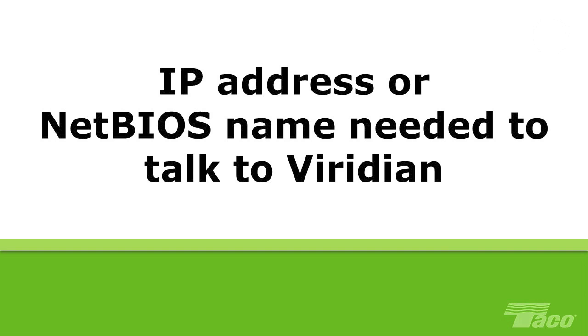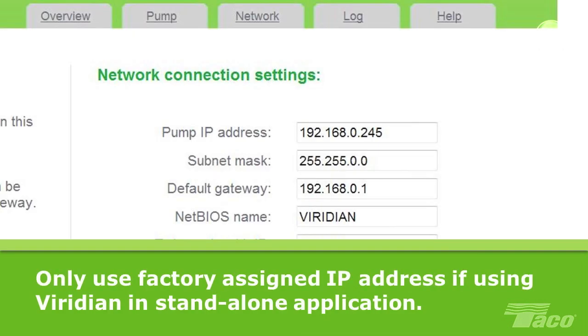As it will be extremely difficult to communicate with Viridian or to control its operation if you don't know either the pump's IP address or NetBIOS name, it is highly recommended that any changes to the pump's IP or NetBIOS name are recorded. All Viridian pumps are shipped from the factory with the same generic IP address, 192.168.0.245. You may continue to use this IP address only if you are using the Viridian in a standalone application.